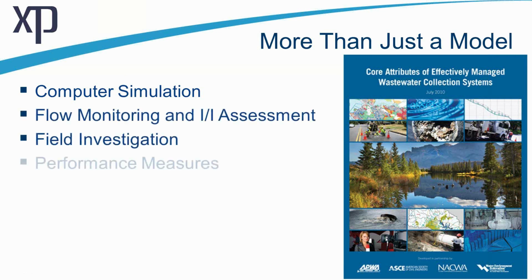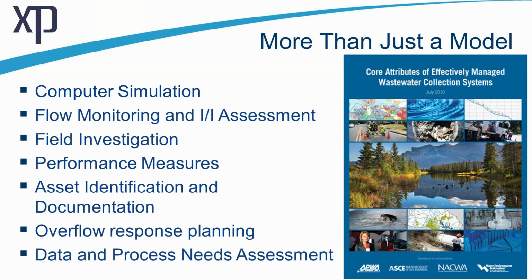But look at all these other elements that are part of an effectively managed wastewater collection system that are kind of built in as part of a sanitary sewer model. You typically will have flow monitoring and you'll have some I&I assessment because that generally drives the capacity. That will require some type of field investigation, and it's a great opportunity to refine those processes. There are usually performance measures that are built in to help define solutions.